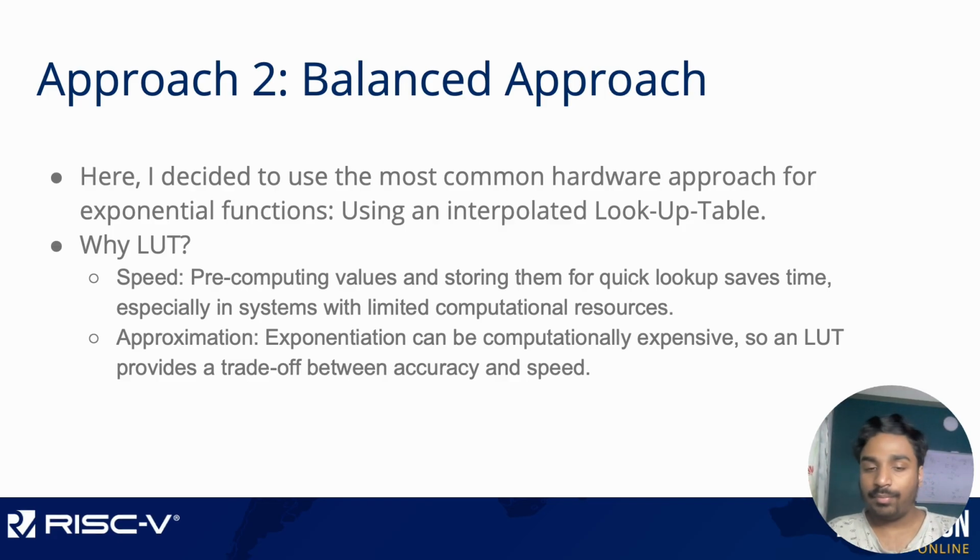So for the second approach, I took up a very conventional lookup table approach, in which I implemented an interpolated lookup table, where using the lookup table gave me two advantages. First of all, the speed. Since I have pre-computed a lot of values and stored them in lookup tables, it is very efficient, and usually such tables also take up very minimal computational resources. And approximation: because we have interpolated the answers from the lookup table, the answers won't be as accurate as the previous implementation, but they'll make do.